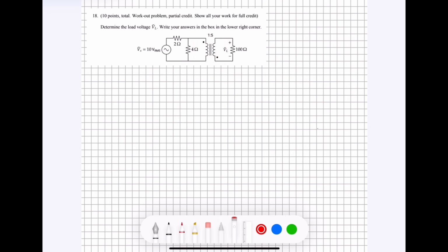It looks pretty similar to a mutual inductance problem. The only difference is these two lines in the middle make it a slightly different kind of concept, but they are very similar. When we're solving this kind of circuit, we have this ratio right here, which is going to be N, and it tells us the ratio between the terms on either side of the transformer.